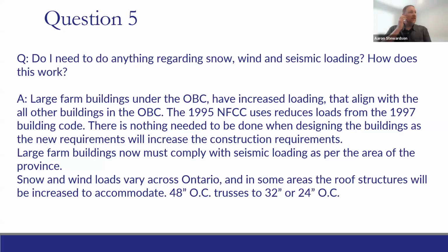Okay. Anything that was small, under 6,000 square feet, you are still back to the 1997 building code loadings, which is very little for seismic and lower snow loads. So the small farm buildings still comply with the 1995 National Farm Code of Canada for that, right?